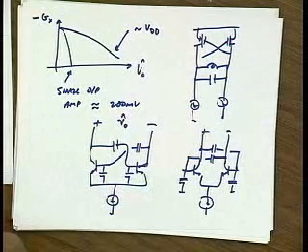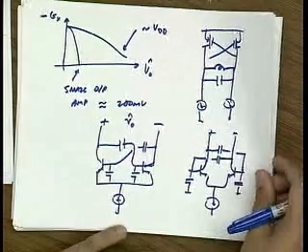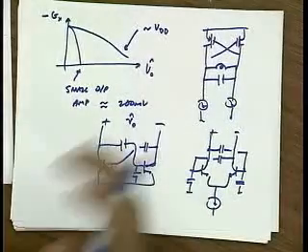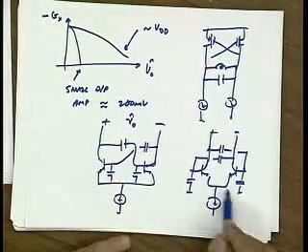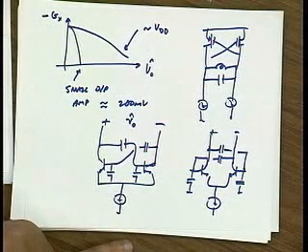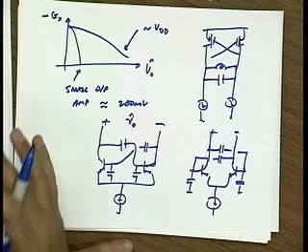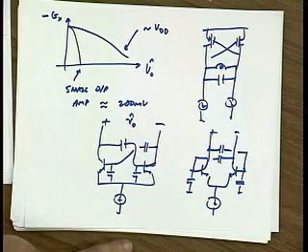All right, questions? Yes, Lee. What's the difference between having a current source and just ground it? Yeah, it's also a very good question. So if you don't ground it, it's exactly what I was talking about. If you don't have a current source, there's nothing limiting the current, right? And so it self-biases. There's a couple of problems with that. First, it's a little bit dangerous because that operating point is going to vary over process and temperature.